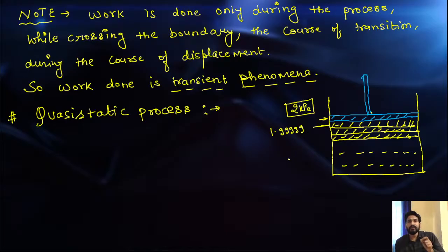Right? So there is a negligible change in the process variables. Is it clear to you? Right? So we are taking infinitely small steps. If we are taking infinitely small steps, then the deviation from thermodynamic equilibrium is negligibly small, which means it is not considerable. So we can say that thermodynamic equilibrium is established throughout the process. But for that purpose, we have to take infinitely small steps.